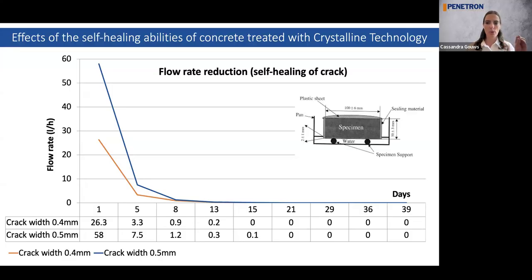Now, what they did, water just freely ran through these cracks and over these samples. And on the y-axis, you see the flow rate of the water in liters per hour. Then in just about 2 weeks, you'll see there's no more water flowing through. So it drastically slows down. And that shows you that the self-healing of the crack takes time, but it does totally self-heal that crack.